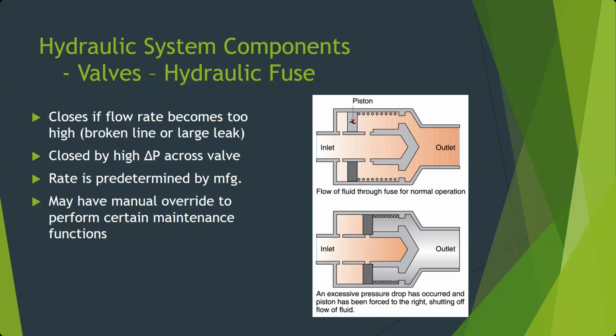So if you pick up a piece of FOD and chuck it into that area, there's a very strong chance that you can damage those. Those hoses are out, they're exposed, and they're near stuff. Okay, so if one of those hoses gets damaged, we don't want to hit the brakes and drain our hydraulic system.